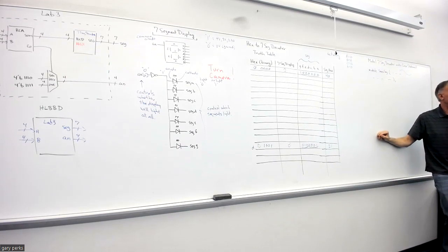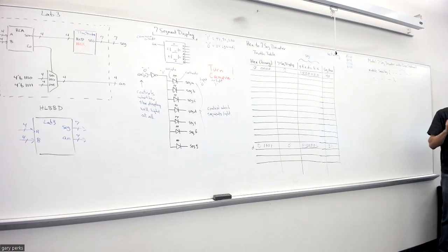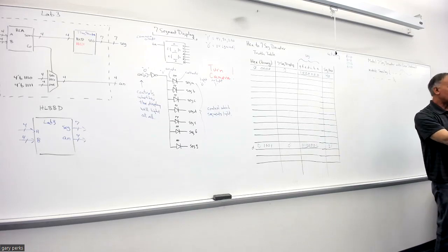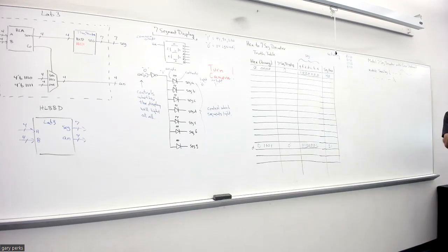Remember what that was that you have to add? Logic. Right, logic. So it's the same thing here. Anytime you have an always_comb block, doesn't matter whether it's an if statement, case statement, or whatever it is, any output within that always_comb has to have logic after output. So for your seg output, you're going to have output logic, and then your seg output is 7 bits, so you have [6:0] seg. And you'd have to do the same sort of thing for AN, the anode output.